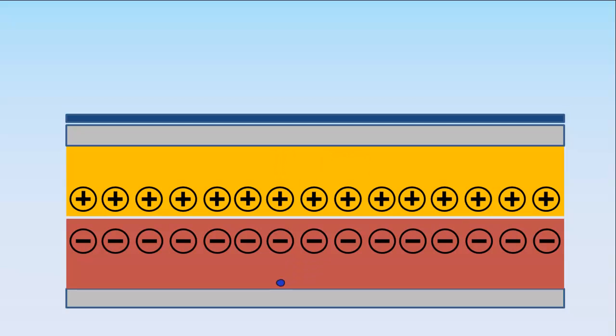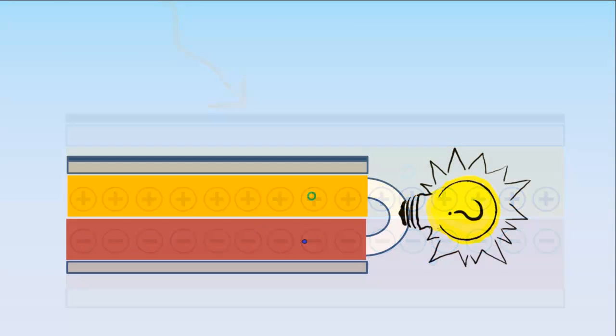The PN junction will only allow electrons to move in one direction, from the N layer to the P layer, because of repulsive forces. When a photon hits a solar panel, it can excite more electrons in the N layer. These become free for conduction. If the photon has enough energy, it can excite the electron across the barrier at the PN junction, over to the P side. The electron which has crossed the barrier is separated from its hole. It wants to recombine with it, but it can't.